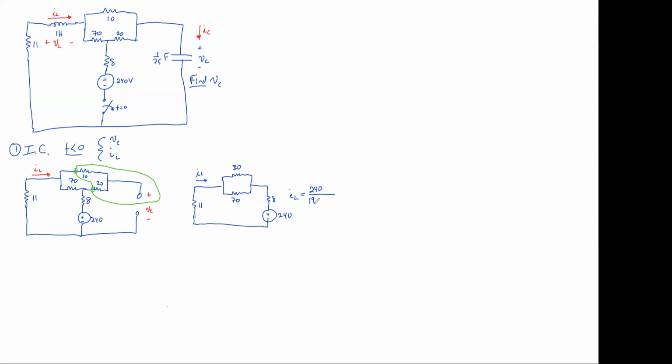It is a current divider, but when you're calculating equivalent resistors, what is it when you've got 2 resistors and they're joined at both ends so that the current splits through them, but the voltage is the same across both? Oh, parallel. So we need to put those 2 in parallel. So that's 30 in parallel with 70. And that's almost correct except for one thing. Jonathan, can you tell me what the one thing that's wrong with that equation?